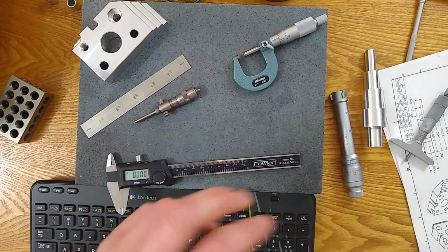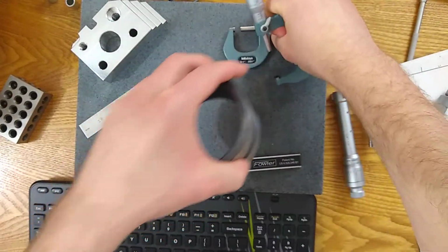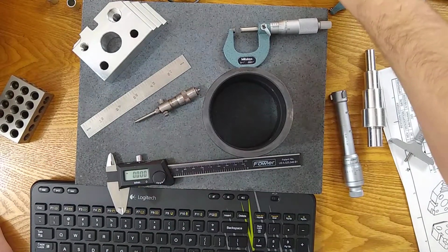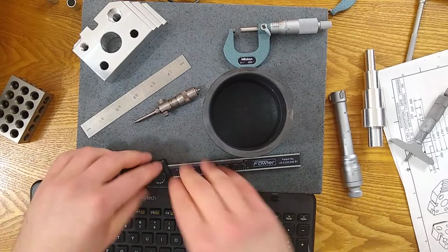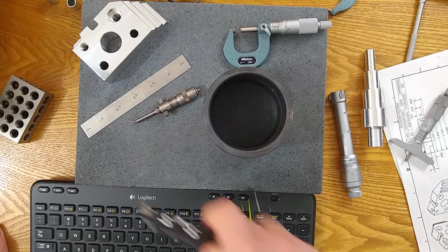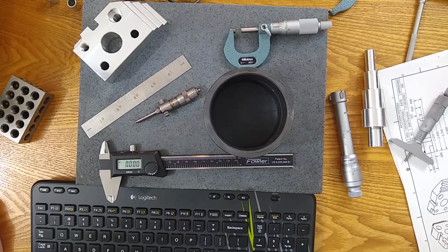So I'll grab a 4-inch micrometer, maybe a 4 to 5 micrometer, and we'll measure across our part, and we'll take a look at what we get. The micrometer said 4.0146. Okay, so we added 6/10 compared to our caliper because our caliper doesn't have that resolution, or that accuracy either. So now we ask ourselves, does 4.0146 mean the part is within spec?